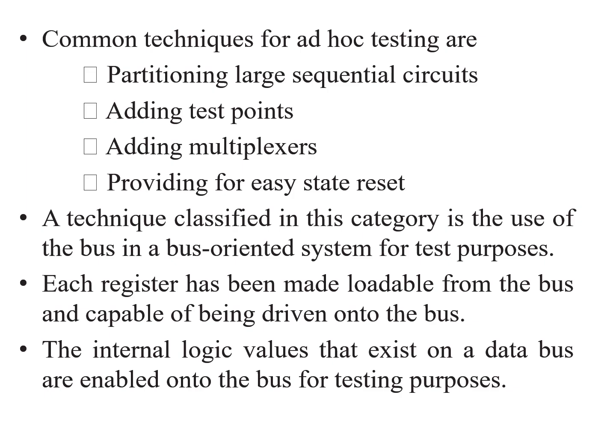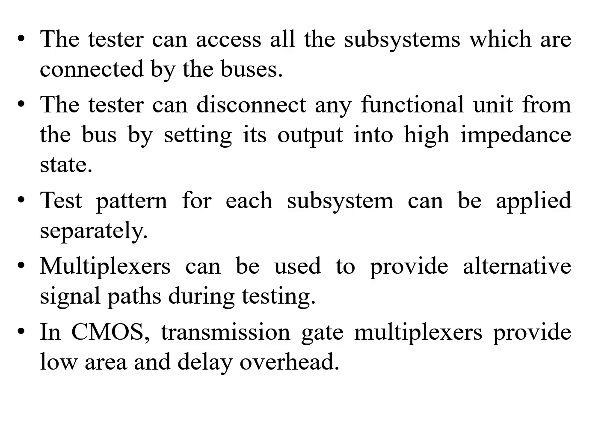A technique classified in this category is the use of bus in a bus-oriented system for test purposes. Each register has been made loadable from the bus and capable of being driven onto the bus. The internal logic values that exist on a data bus are enabled onto the bus for testing purposes. The tester can access all the subsystems which are connected by the bus. The tester can disconnect any functional unit from the bus by setting its output into the high impedance state. The test pattern for each subsystem can be applied separately.